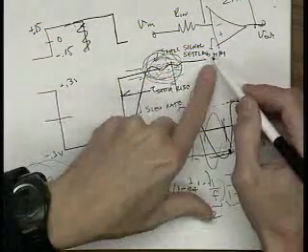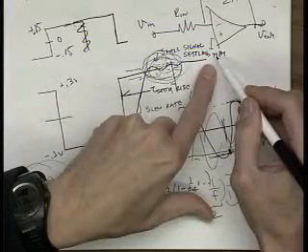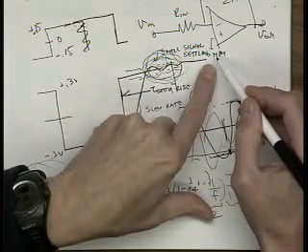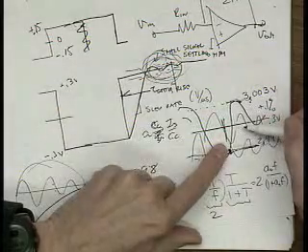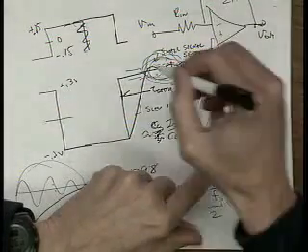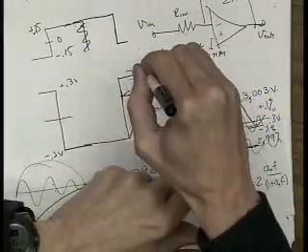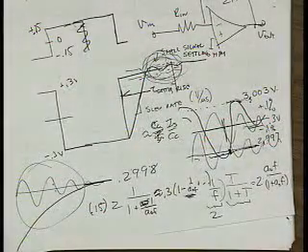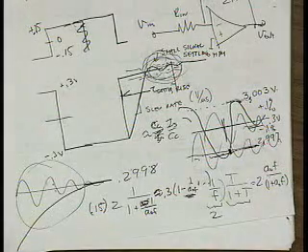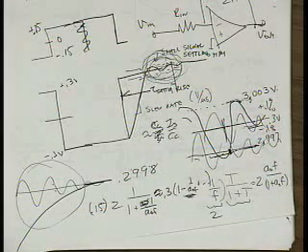And the final thing is the static settling. You want to increase the gain as much as possible to get yourself in the middle of the error bars with the static settling. But of course that will slow down your amplifier, which will slow down your small signal settling time. That's your project. Any questions about that?